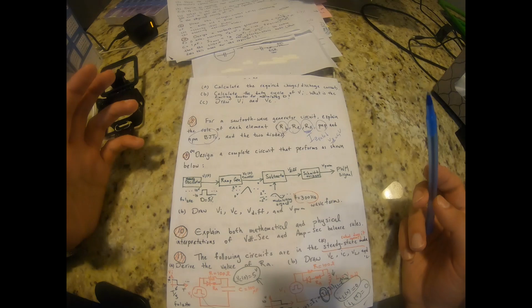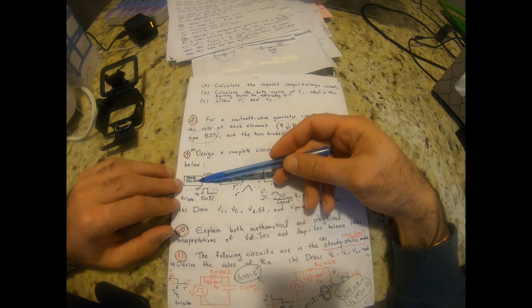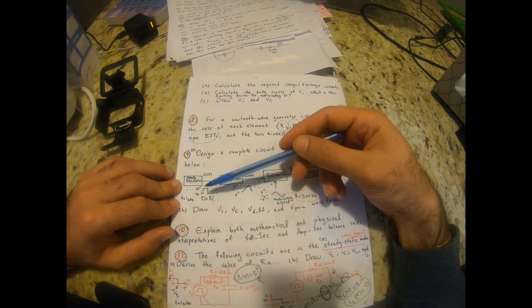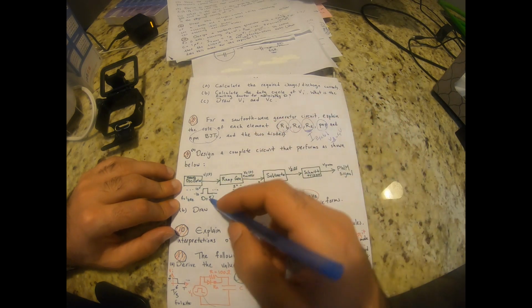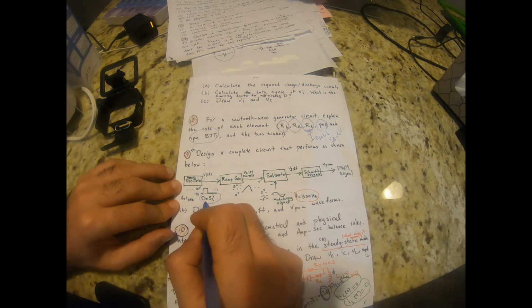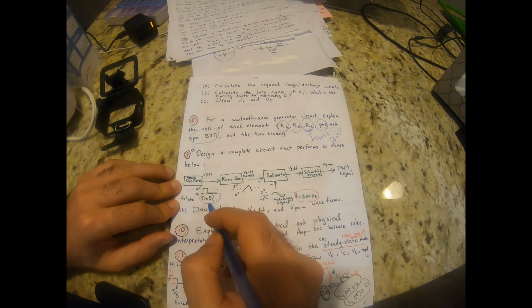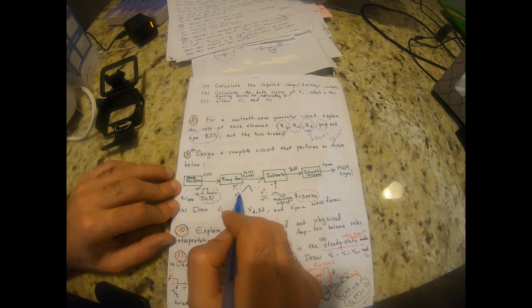Question 9 is basically a combination of many different things that we saw earlier. This one is an astable oscillator. You have the frequency, you have the duty cycle. You know it's going to oscillate between -10 and 10, right? Because the duty cycle is less than 50%, you have to have an extra resistor with a diode. The ramp generator, we did something similar to that. It's similar to the previous question we did. So we just want to have a ramp generator that goes from 0 to 5 volt.